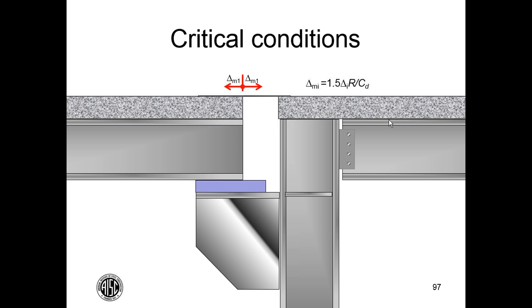We're going to assume the structure on the left can move its full displacement, and the structure on the right can move its full displacement. The gap between these two diaphragms, it's probably a good idea to size it for that, but the main thing is maintaining support for that maximum separation. So for purposes of that bearing length, we need to calculate the bearing length that we need and add to it the expected relative separation of these two. So that's a very big corbel.